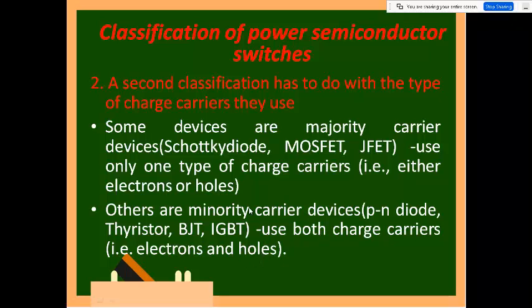In minority carrier devices, I repeat, after turning on you lose the control, and only the external supply has the control. So when this external power itself goes to 0 every 10 milliseconds, automatically the device gets turned off.